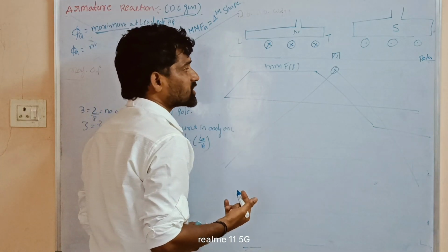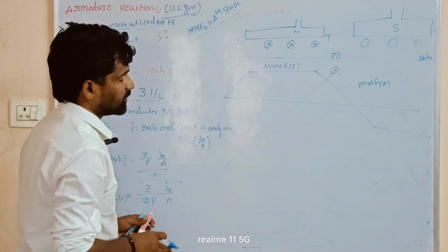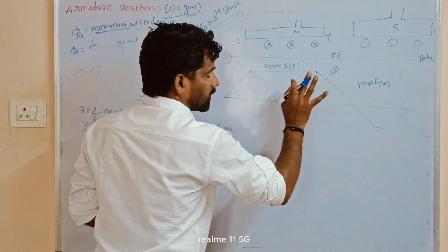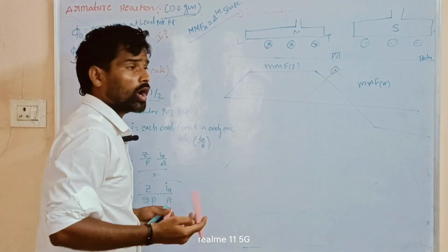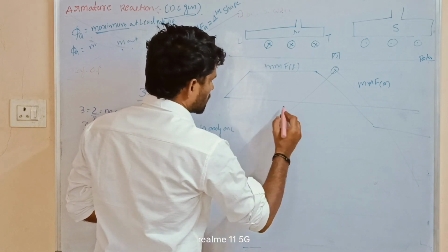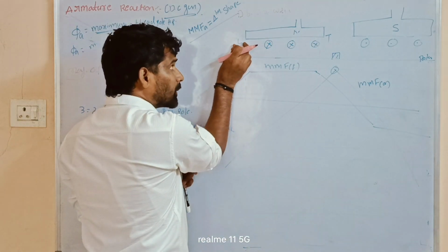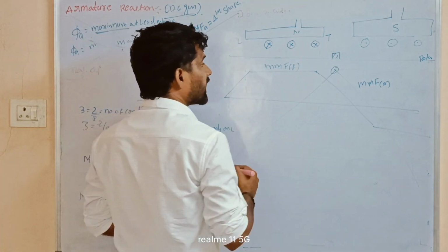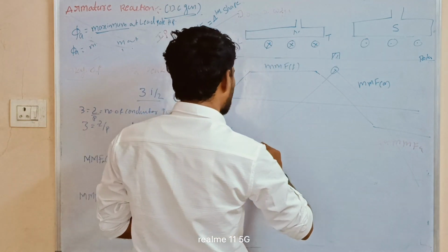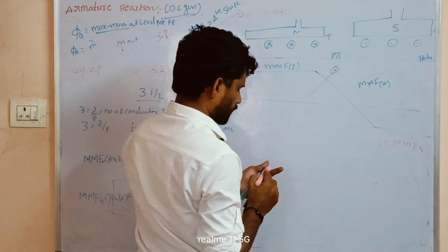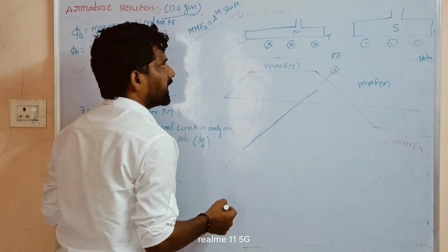Now the resultant. What is armature reaction? Armature reaction is the interaction between the field MMF and the armature MMF. From this reaction we can find the total armature reaction. Between the leading pole tip and the trailing pole tip, with a uniform air gap, the armature flux is directly proportional to MMF A. That is a linear condition, with no change up to here.